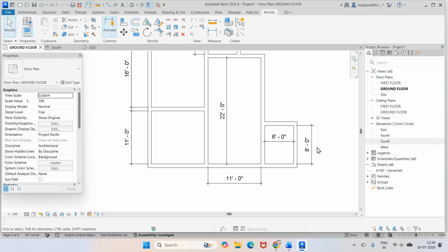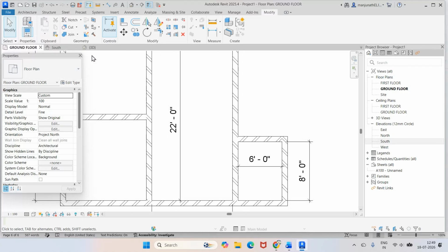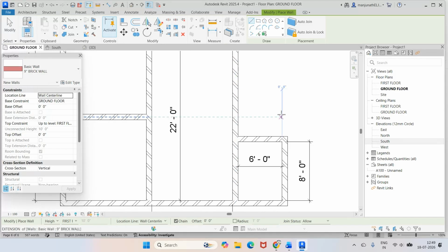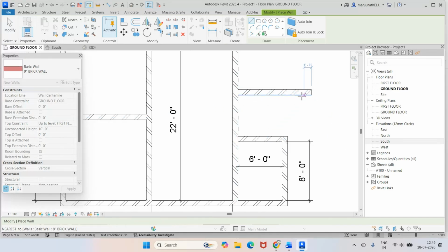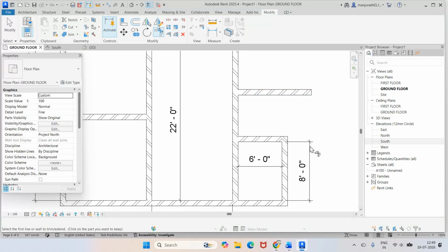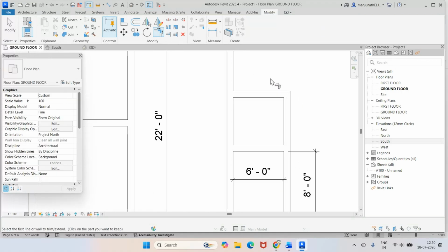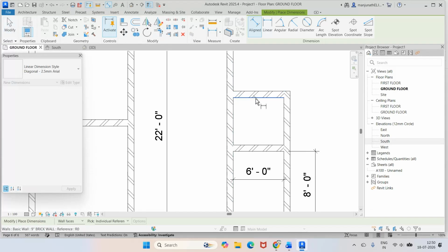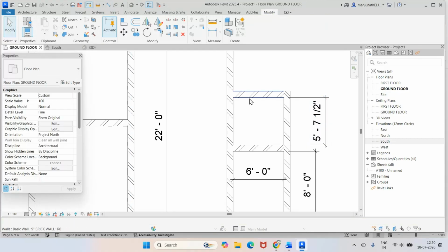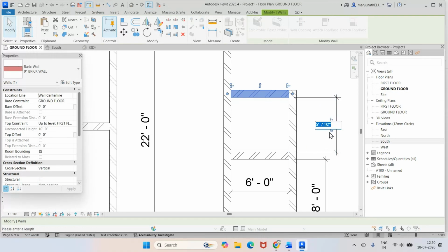So to do that, here I will go for WA, which is the wall, take this dimension and then draw this. And go to extend the trim corner between these two now. So 6 feet by 6 feet. So I want the dimension between, sorry, I want to go for DI. You select between this and this. You give the dimension as 6 feet by 6 feet. Okay.